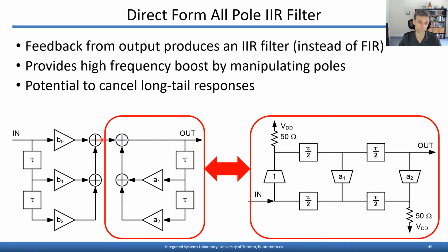So we focused on the IIR portion of the response in this next work because the FIR portion had already been described with traveling wave filters. And we realized that you can use distributed circuit techniques and LC ladder delay lines to realize a structure like that.